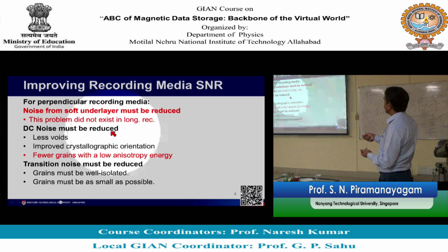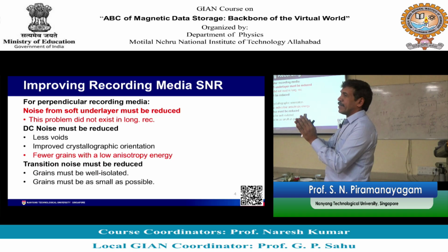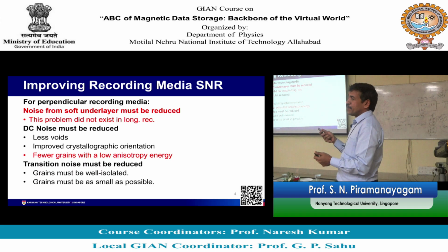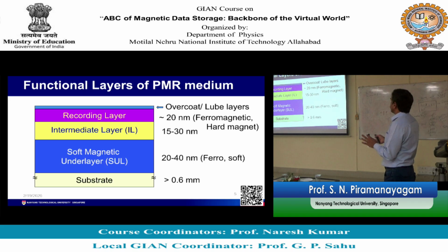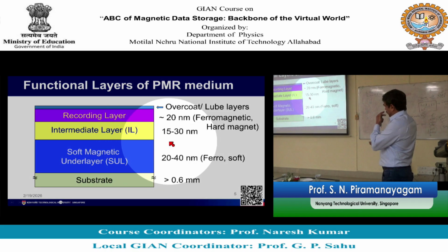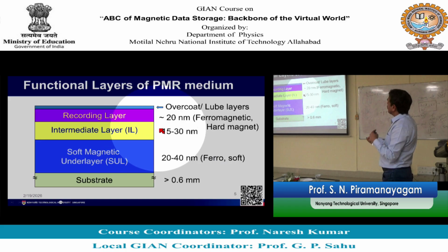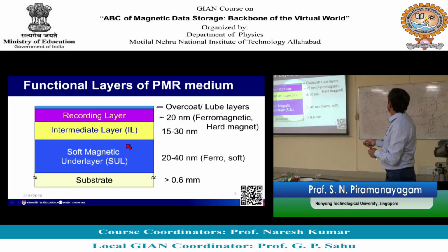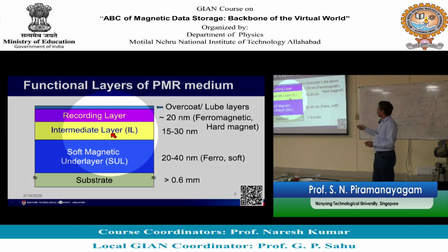Okay. The noise will be higher, and moreover you need to make the sample sit in the sputtering chamber for a longer time to deposit a thicker film, which is unnecessary. You are spending more time, more money, which is not necessary. So, there is an optimum thickness. Similarly, same thing here. If you make these intermediate layers thinner than a certain thickness, then you cannot make the C axis of the cobalt perpendicular. So, there is a lower limit.